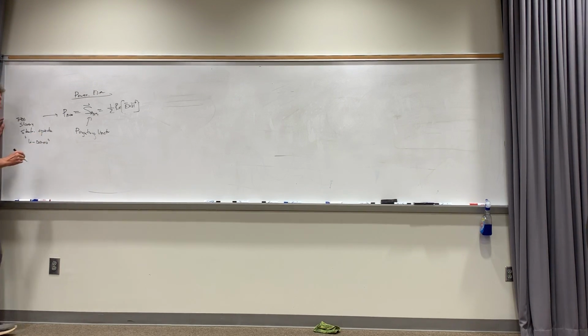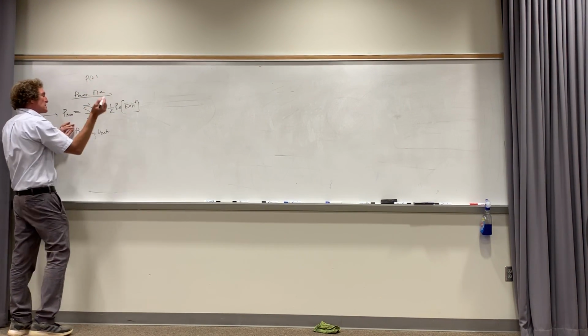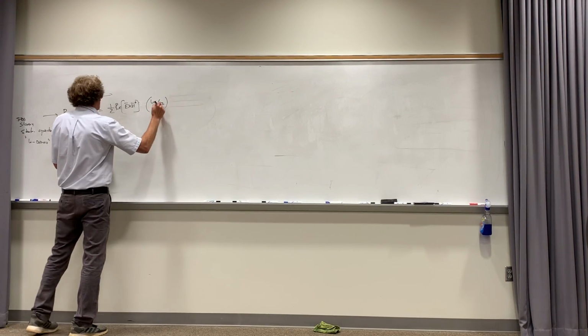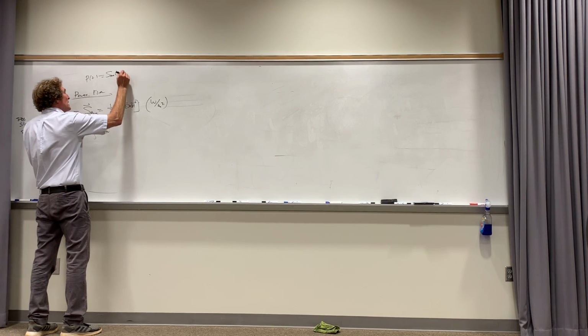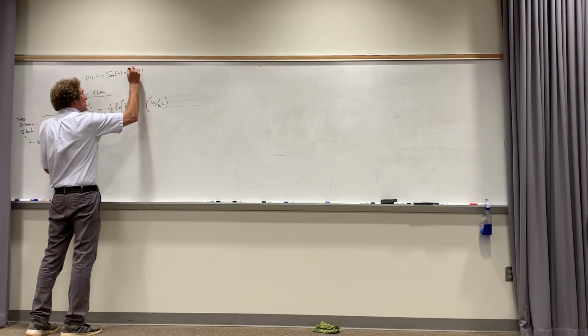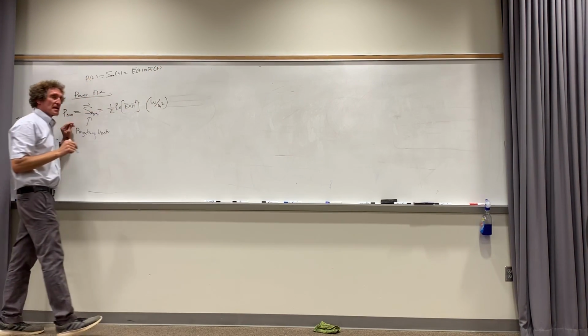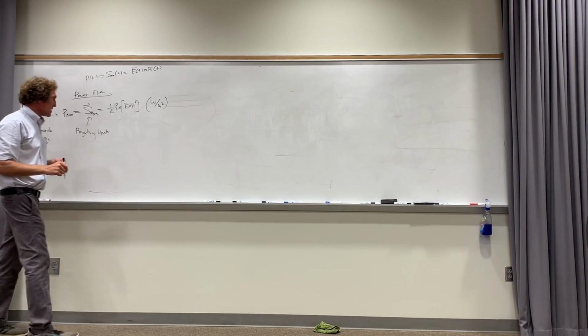It's not instantaneous. This is only for steady state, but that's the most common way it's done. Instantaneous power flow, P of t, and this is in watts per meter squared, by the way. Instantaneous, S_AV of t, is simply E of t, vector crossed into H of t, vector. There's no conjugation. That's instantaneous, but almost always use steady state power, or average power.